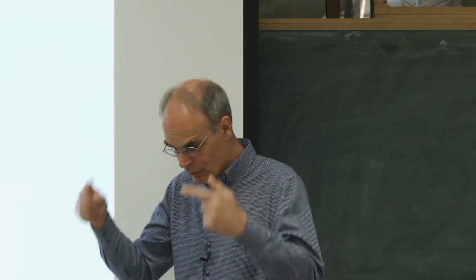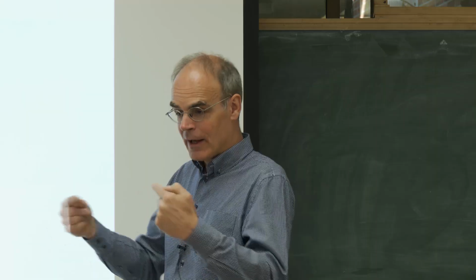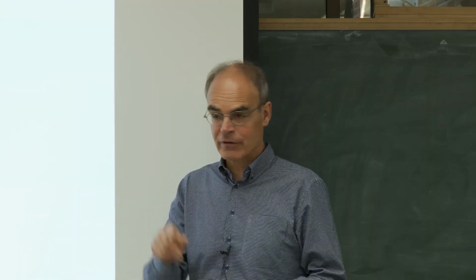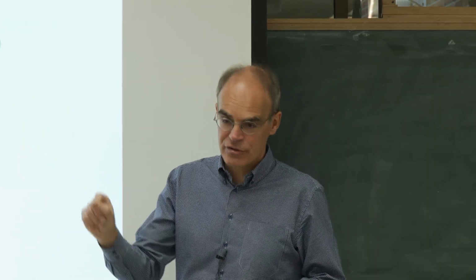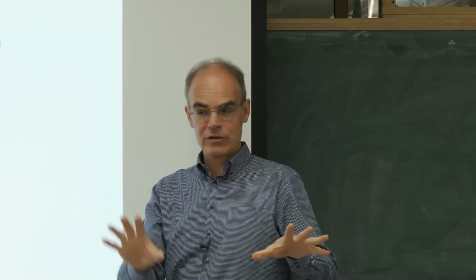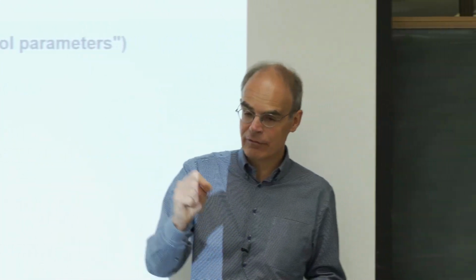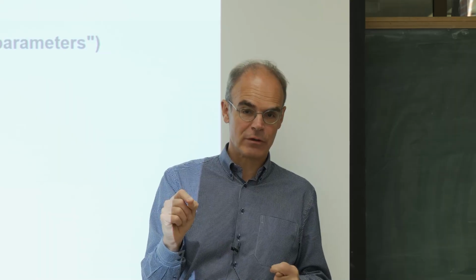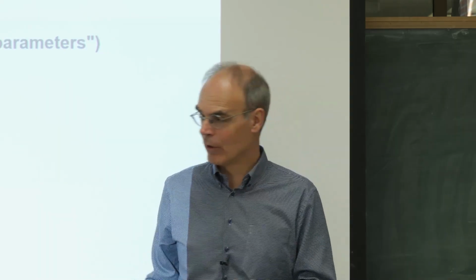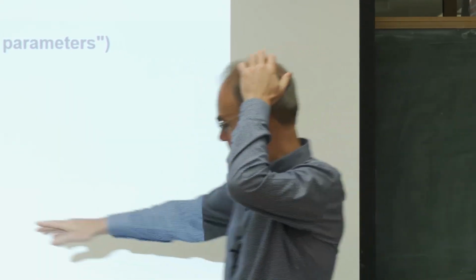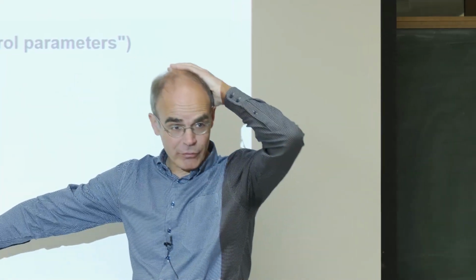For safety reasons first, and then secondly to control product parameters, the purpose of extrusion training is not only to know how to program the thing and how to build it together, but also to get a feeling for the feedback loops in the extruder. Yeah, we'll probably do some scenarios. So pressure, product temperature, also really critical.